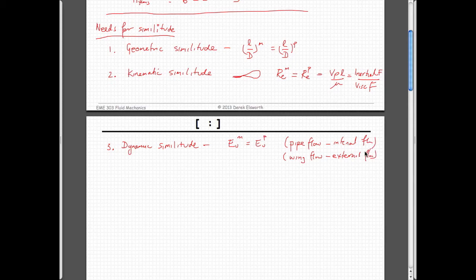In a pipe, you're interested in flowing inside the pipe. You don't care about the fluids on the outside. And the other one would be the Froude number. I'm never quite sure how to pronounce that. And that is for boats, so with a free surface. In other words, if you have a water tank and you pull a boat through it, and you measure the forces you have to apply to pull the boat through at a certain speed, then the information that you might want to process is relative to the Froude number. And so these are, very simply, the deals.